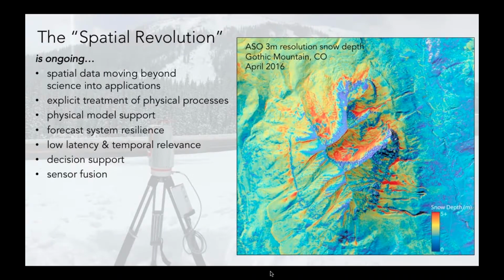They've been great partners in exploring the utility of these data to their operational system. We've been refining our processing to get fast turnaround data delivery. Data latency is really important with the snowpack since it can change on a very rapid time scale. And then neighboring basins have been watching quite intently, and we are now flying quite a few more. So we've been able to generate this total basin aggregate snow water equivalent volume multiple times through the melt season for multiple years, spanning the driest year on record, 2015, through the wettest in 2017, and some years in between.